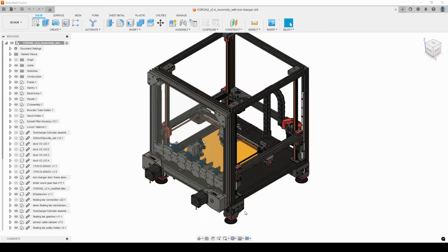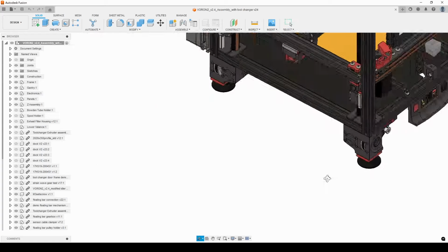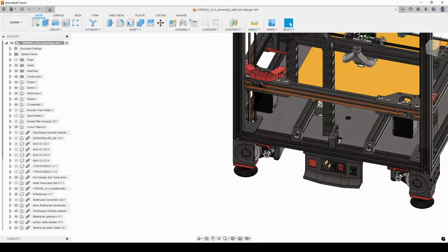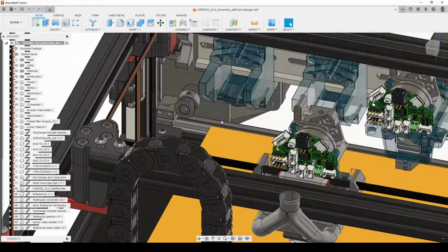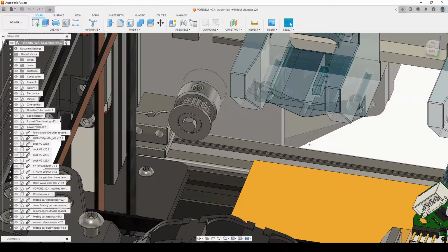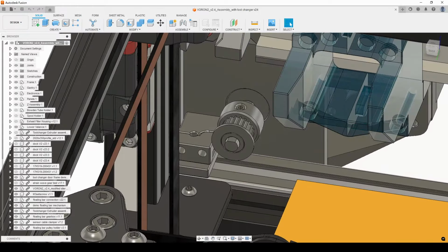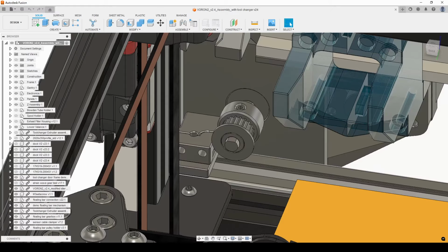Based on the current design, the width of the space is approximately 12 mm, meaning that the coiled cables should be at most 12 mm in diameter. The sensor cable has a diameter of 2.5 mm, resulting in the winding sections being at most 7 mm in diameter, allowing for some tolerance to ensure a better fit. I chose a bar diameter of 6 mm for coiling the cable.